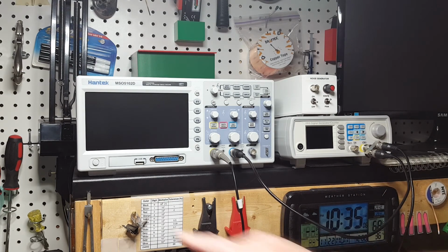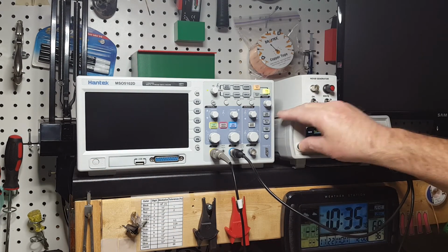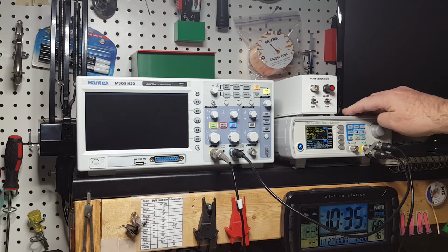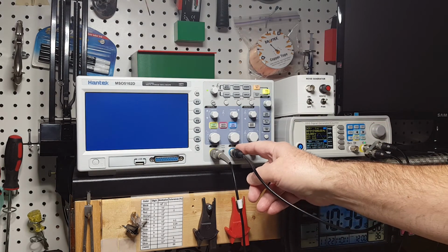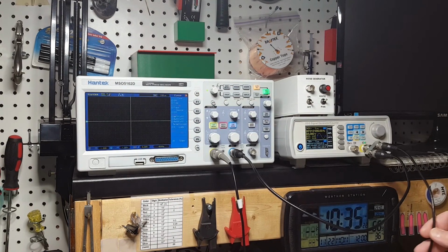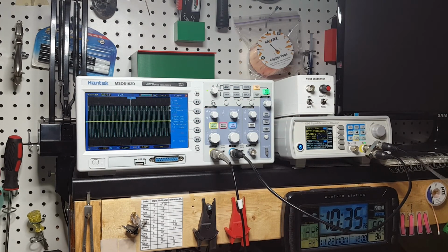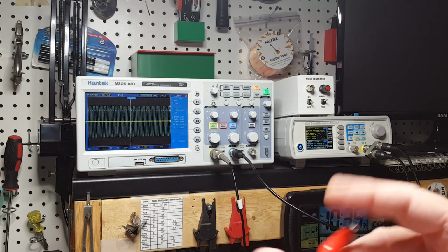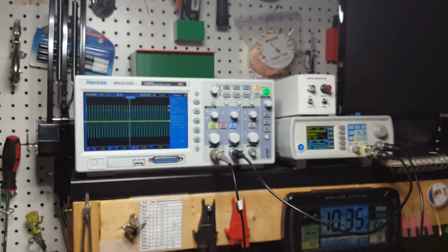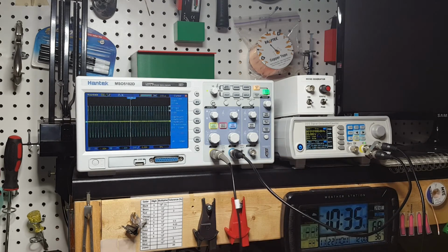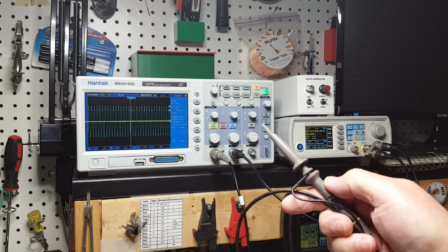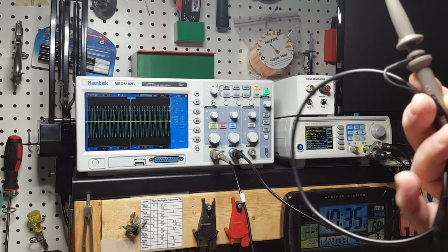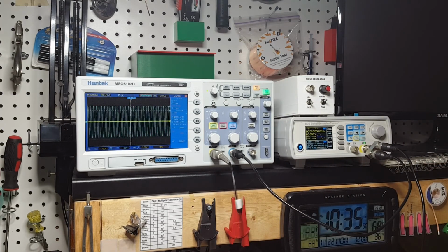Here is the setup for the experiment. I will be using an oscilloscope and a function generator. The output of the function generator goes to channel 2 of the oscilloscope, so we can see the input signal on it. The same output of the function generator, through a splitter, goes to a cable with two alligators at the other end, which we can use to inject the signal in the circuit under test. The other channel of the oscilloscope, channel 1, is connected instead to a probe, which we will connect to the output of the circuit, and so we can visualize the output signal of the circuit. This way, we will be able to compare the two signals.